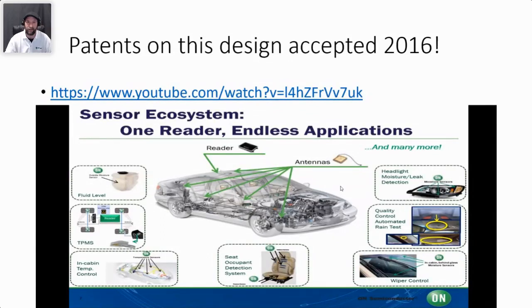We're starting to see some newer things that are out there, but what I really wanted to get across to you was that even the simplest of systems, obviously, can make you not only sit there and chase your tail sometimes during the diagnosis, but also surprise you with what they have. That seat sitting switch, that's a key thing, right? That's not in the initial pictures. Those are the things that if we didn't know they were there, we would wonder, how did it set that seat weight sensor code? We like to try to find out all the hows and whys and whats in this business. And I think that was one of the things that hopefully I was able to get across to you.